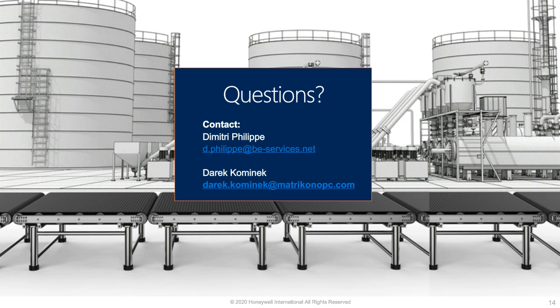Yeah, sure. I would say it very much depends on two things. One would be the power of the CPU that is used on the PLC, and the second thing would be the scan rate for these 50,000 tags. If those need to be exposed over OPC UA every millisecond, of course, that will require a lot of resources from the PLC. So I guess it's necessary to do tests.